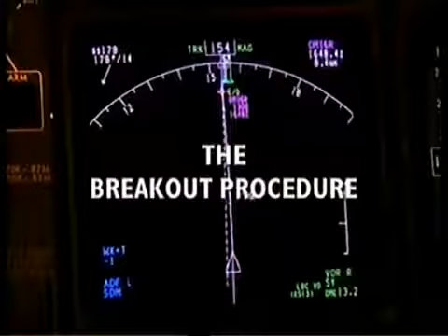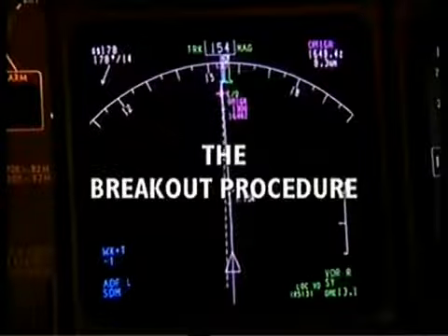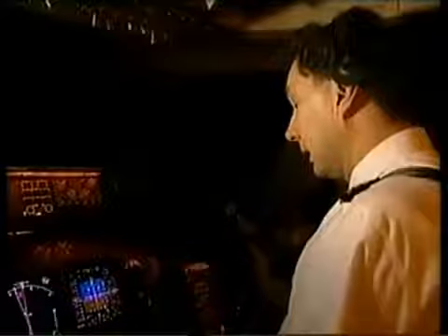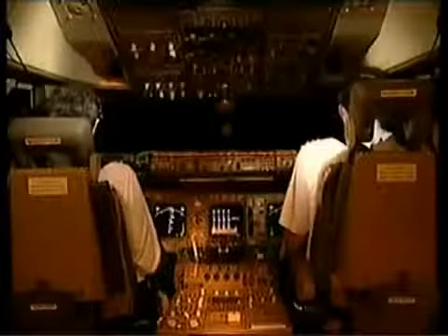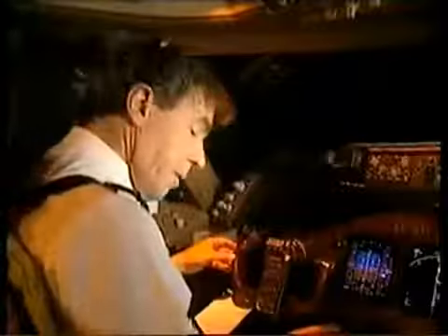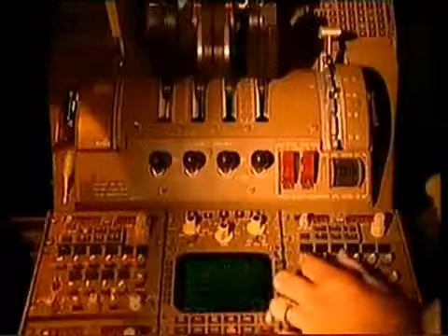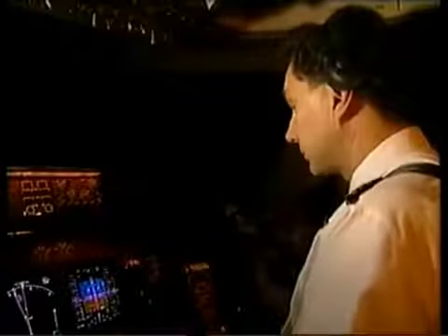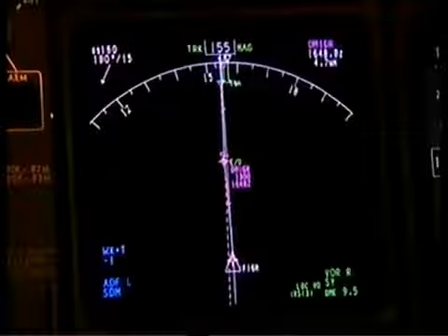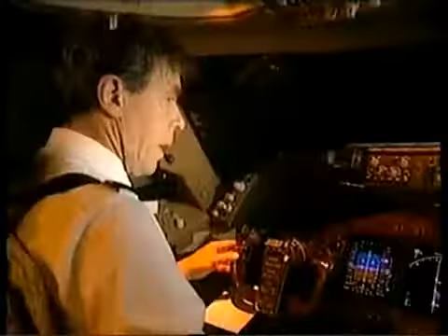Oscar Juliet Alpha cleared for ILS PRM approach runway 16 right. Call tower 120.5. ILS PRM approach 16 right, 120.5, Oscar Juliet Alpha. Okay, monitor the PRM frequency. Volume's the same. All completed. Landing checklist. Go ahead. Speed brake. Arm. Landing gear. Down. Flaps. 25. Landing checklist complete.